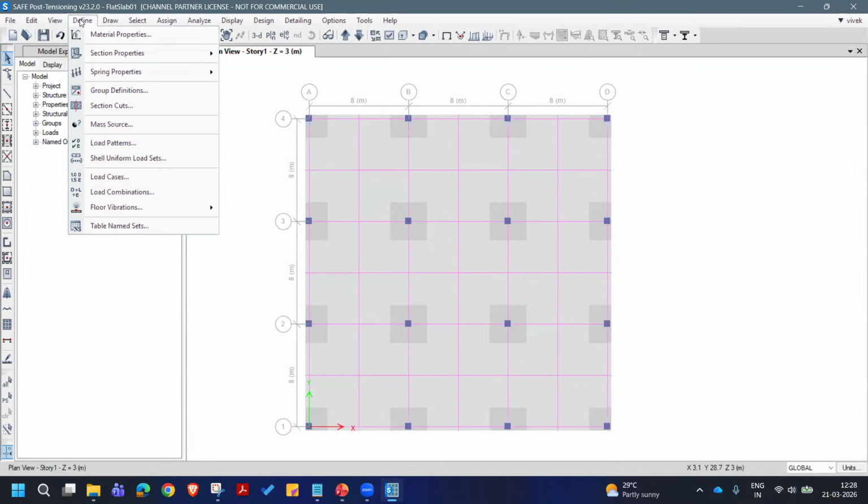So the program performs an elastic analysis, calculates the moments, and then determines the reinforcement. And the reinforcement can be utilized directly from the design result, or the user can specify. Both are possible. And internally, it then calculates the cracking moment. And an interpolation coefficient is calculated to determine the curvatures between the fully cracked and uncracked states, and then computes the curvature for the applied moment,